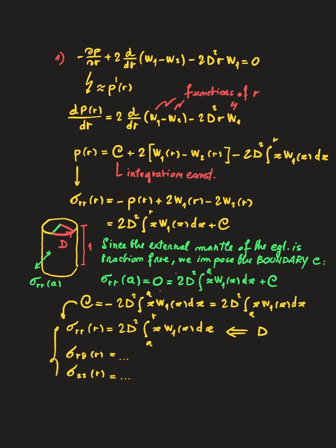Now, what do we use these for? Did I tell you in the beginning, when I subject this cylinder to torsion, I'm doing something. I'm holding the height fixed. So if the cylinder, for example, wants to elongate, what do you think will happen? It is exactly the same effect that you have seen in simple shear. If you keep the height of this cylinder fixed, if it wants to elongate, you will find compressive forces on the upper and lower bases. So let's try to see if this is the case.